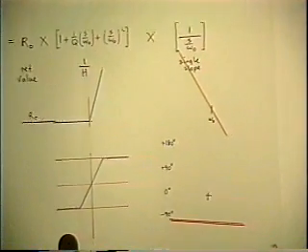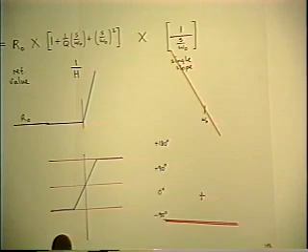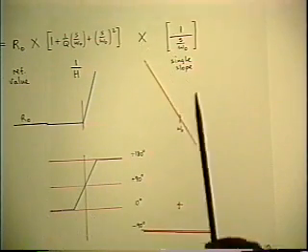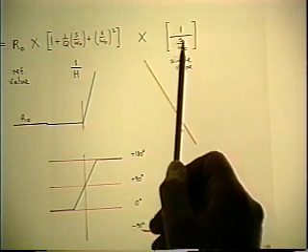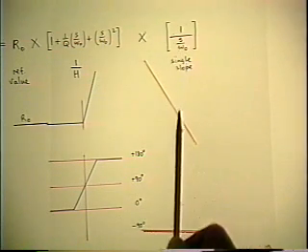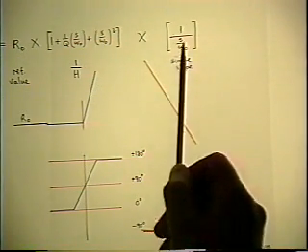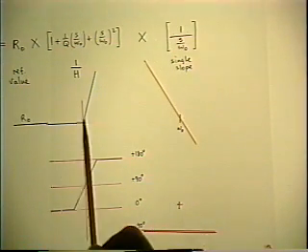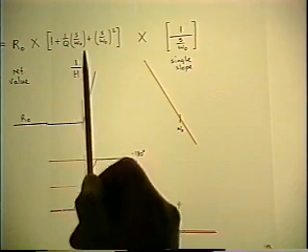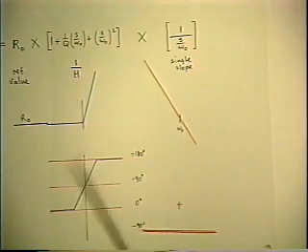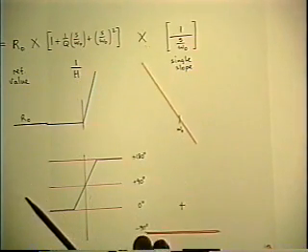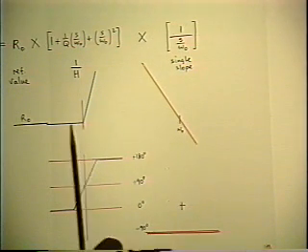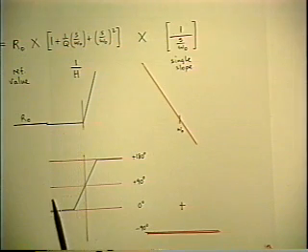Move this a bit further over. Okay, vertically, I position this because the frequency dividing the S is omega 0. So that's the frequency at which the magnitude of that function is unity. So I have to match that against the 0 dB level I've already have for the 1 over H. So I put the vertical position so that the omega 0 position horizontally lines up with the blue line.